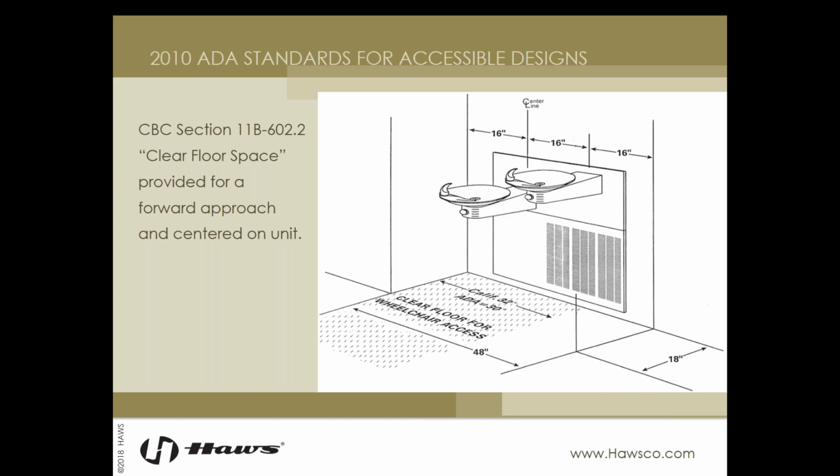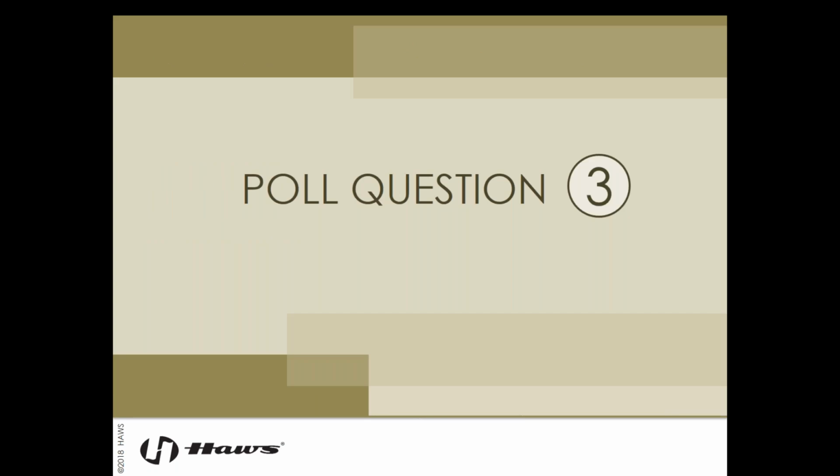Since there's no obstruction under the high side fountain, our primary concern is that wall. If it is at all intruding into our floor space, the alcove would need to be redesigned, or the fountain moved over so that the high side is closer to the alcove, which may not be as aesthetically pleasing, but it would be compliant since the ADA doesn't give us floor space dimensions for the high side of the fountain. But we need to remember that this side is for those of us with stooping disabilities. So we need to leave room for walkers, canes, and other devices that might be used, etc.